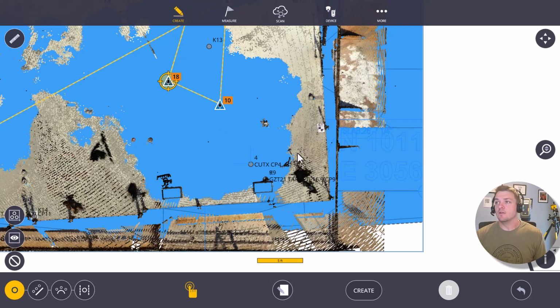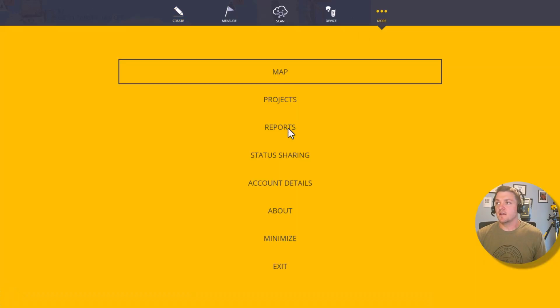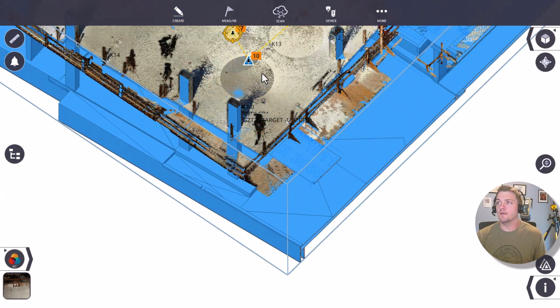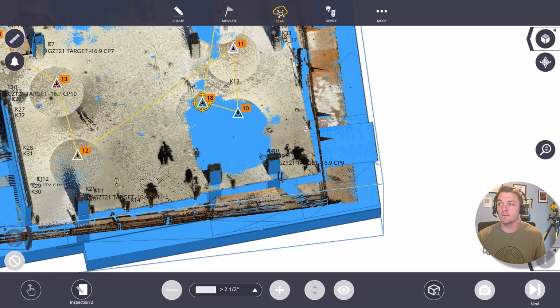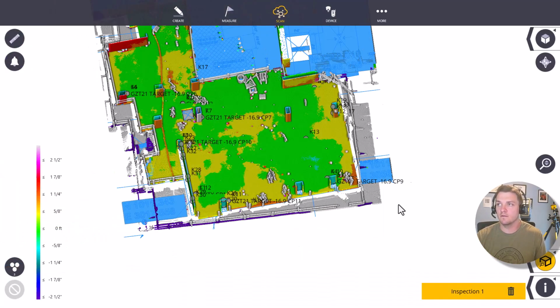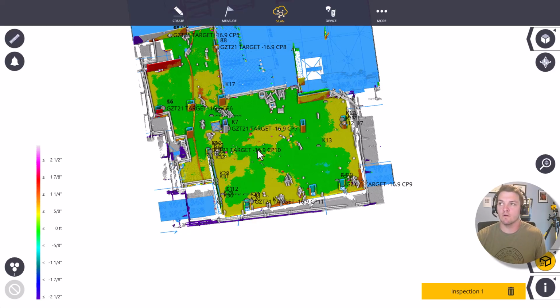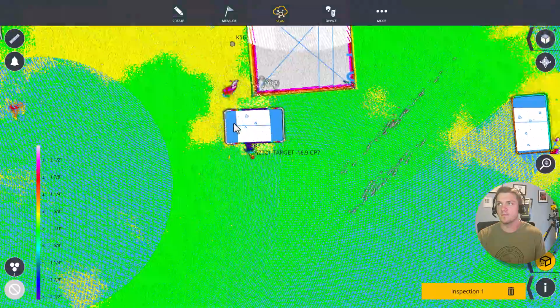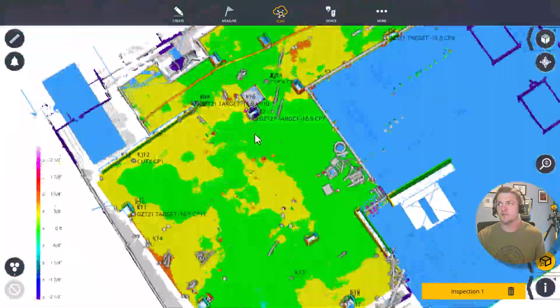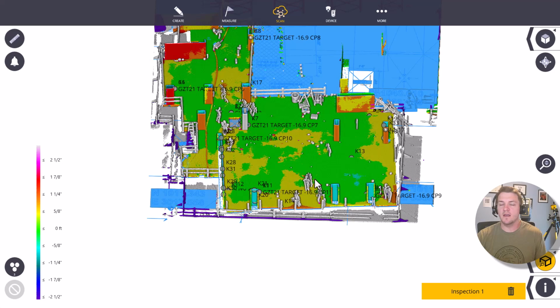So here you can see we have some scan data and model data. Now I could manually align this, and we'll link to a video showing you how to do that and run an inspection to see, hey, is my scan data georeferenced correctly? And this will generally show me blunders like you see here, a shift in how that column was actually laid out. But the problem with that is there's no residuals, so we don't know the accuracy.